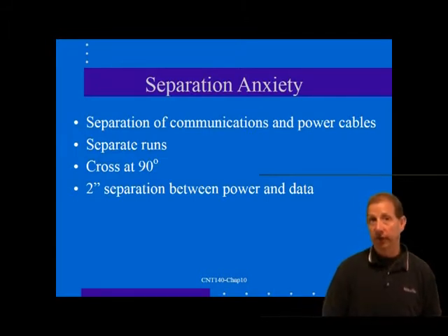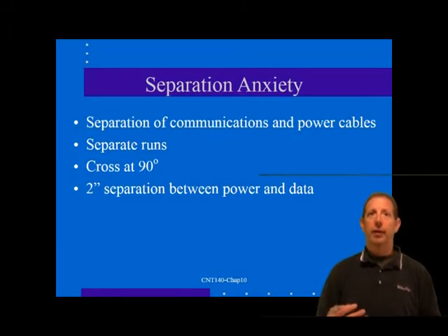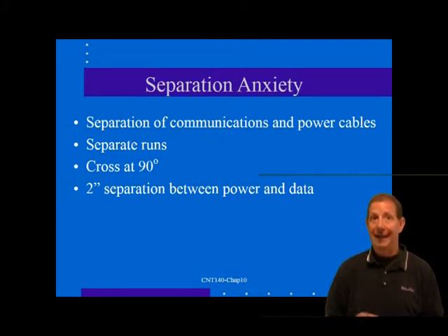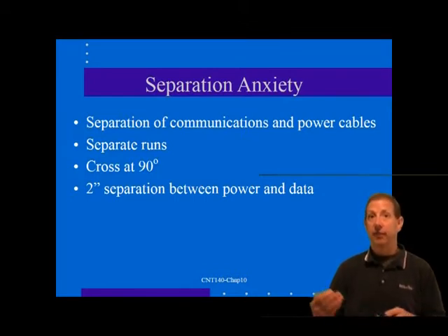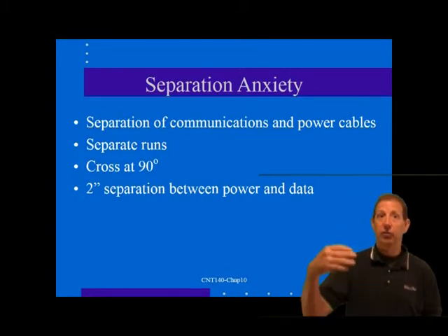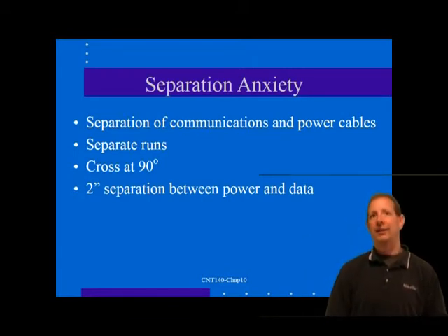The NEC also specifies a 2-inch separation from electrical light, power, and other Class 1 circuits, except when they are in a raceway or metallic sheath, or where they are separated permanently. For example, a LAN cable and a power conductor can be contained in the same power pole or modular furniture pathway if they are run in totally separate raceway sections. The main idea to get from this discussion of power and data separation is that you need to keep power and data cables widely separated, except in that last run through the modular furniture fixtures, where the cables must be placed in separate raceways.